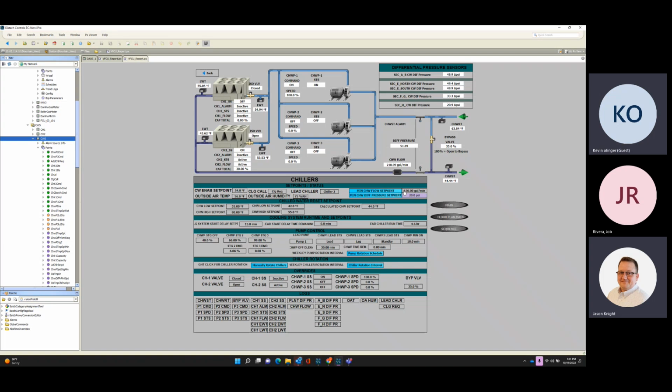Okay, so I looked through BACnet. Well, guess what? Carrier got rid of the pressure sensors on their machines, and they just use a thermal dispersion switch for their flow switch. So I can't read through BACnet whether it's 6 pounds, 8 pounds, whatever. What we found by trial and error is we have a flow meter, because you pump through the machines no matter what in your plant. So we have a flow meter coming back from the machines, and if I go below 150 gallons a minute, the machines trip out. It doesn't matter if one or both is running.